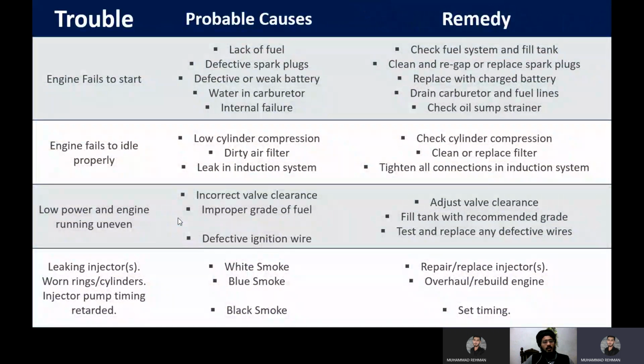These are the few points that we have already seen, what the trouble is and what has to be done. First of all, we will check the first point: what you have to do if your engine fails to start. You have to first see these causes. These causes are written in the checkbook or the related notebook of the engine. If there is lack of fuel, then the engine fails to start. If there is a defect in the fuel injector, then the engine fails to start.